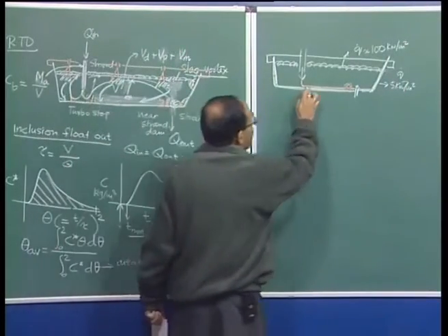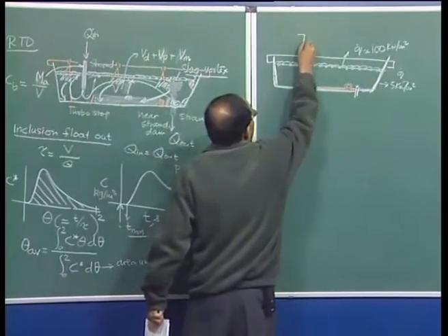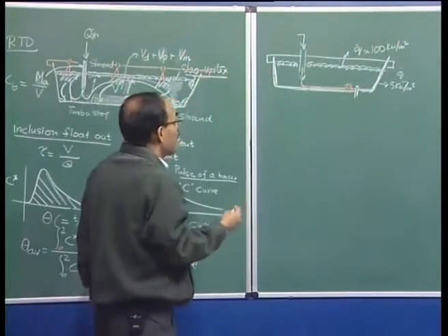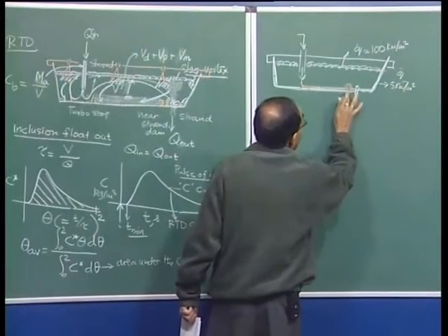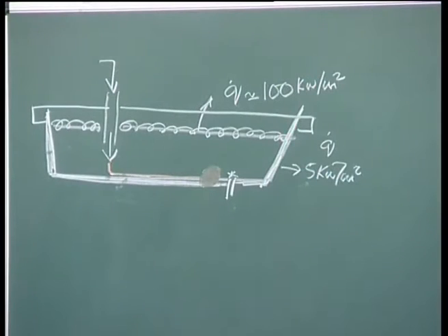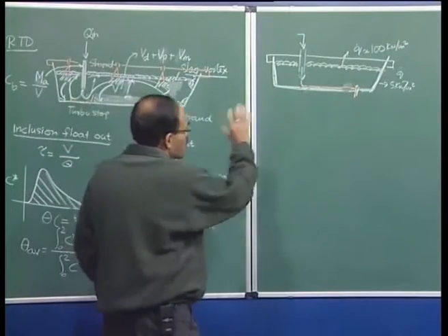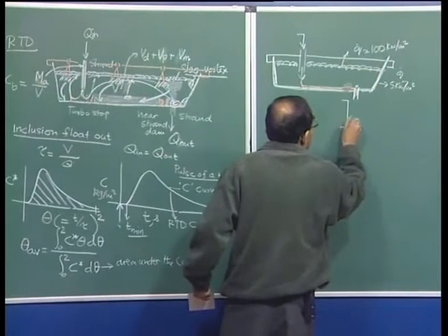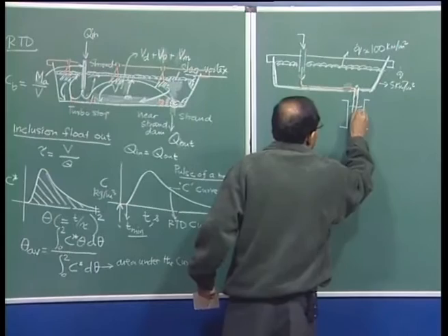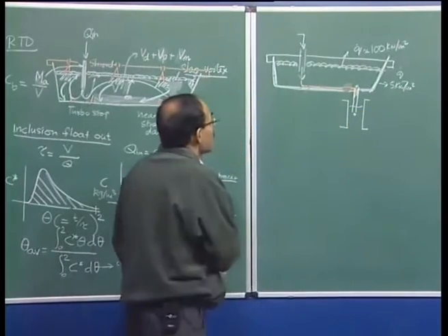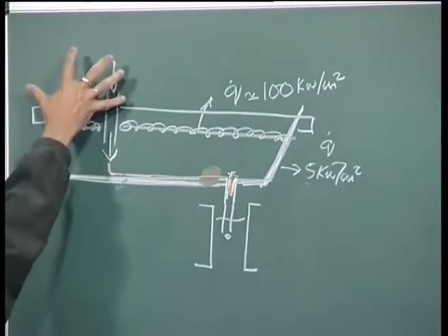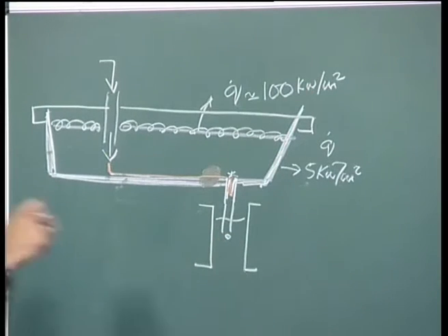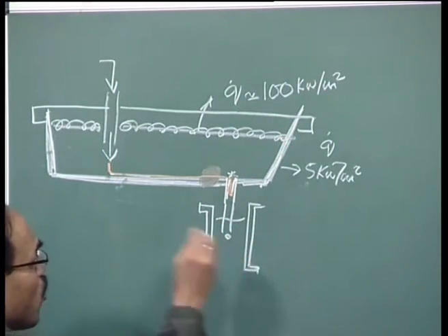So, to prevent premature solidification, what people do is pour in molten metal, or the metal in the ladle is significantly overheated, or overheated to some extent at least, to compensate for this heat loss, such that the material can flow uniformly and then flow out through the exit nozzle itself. Now, because the process control is not tight enough, what happens is that we may land up with material in the mold which has a higher temperature than is desirable. To compensate for this heat loss, we arbitrarily increase the temperature by 20 or 15 degrees, and as a result the material entering the tundish, entering the mold, this is the continuous casting mold, may now have a somewhat larger temperature.